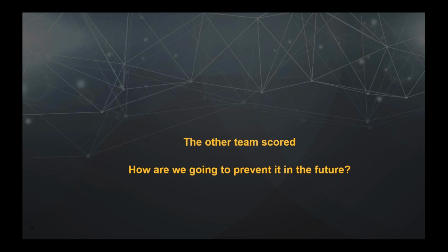Now I've got a question for you. For the FMEA, what's the best way to capture the results? And can you reuse the FMEA or adjust it for other equipment? Well, first off, the way I like to do it is I like to look at the as-found risks: frequency, severity, predictability. And then I look to see what I expect to get once I have put in some improved strategies, if you will. I should see a reduction in that risk. And I like to plot those out and show the reduction in risk compared to the initial, and show that I don't have any truly high failure potentials because I'm attacking those with proper strategies and bringing down to a more acceptable risk level.